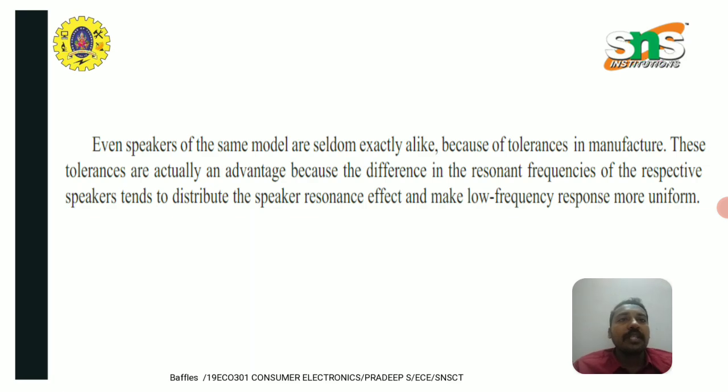Even speakers of the same model are seldom exactly alike because of tolerances in manufacture. These tolerances are actually an advantage because the difference in the resonant frequencies of the respective speakers tends to distribute the speaker resonance effect and make low frequency response more uniform.